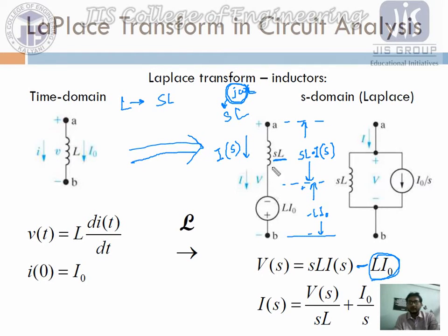So as per Thevenin's theorem, we can say one source is connected with one impedance in series, and we can connect any other impedance as a load, no problem at all. Similarly, if we want to convert this circuit as per Norton's theorem, to find the Norton equivalent circuit, this voltage source should be converted into a current source.